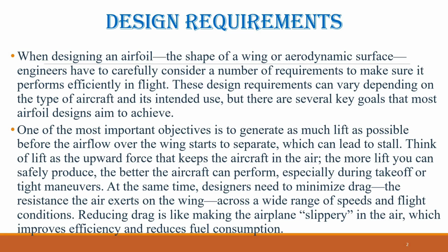For high-speed aircraft, designers pay special attention to the critical Mach number, the speed at which portions of airflow over the wing first reach supersonic speeds. Beyond this point, shock waves and other high-speed effects can increase drag and affect stability, so careful shaping of the airfoil is needed to maintain efficiency and control at these speeds.